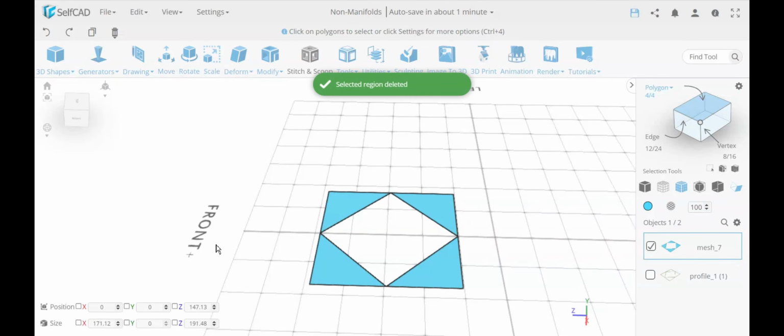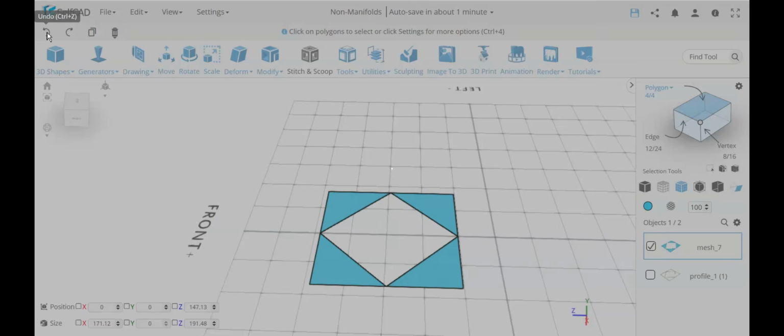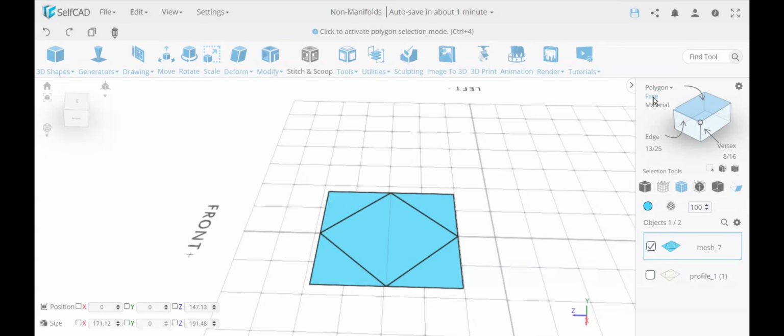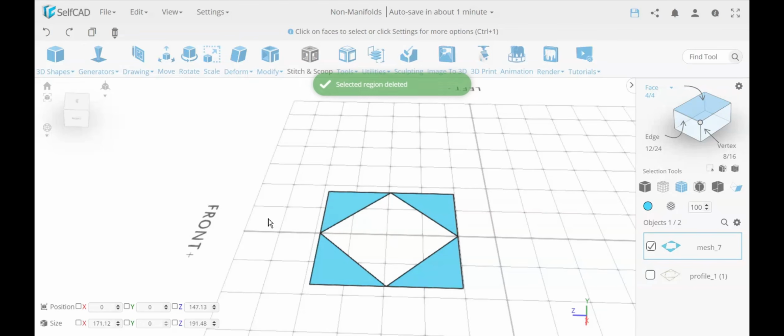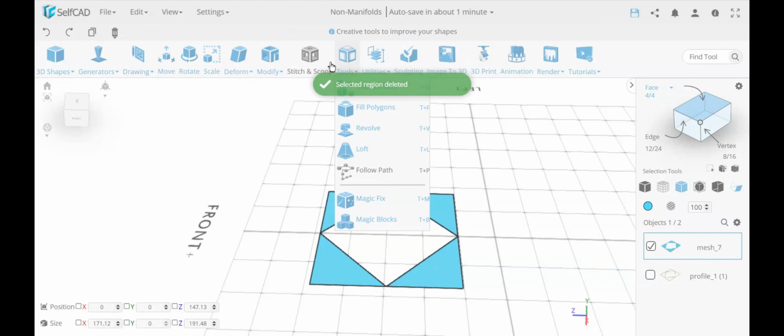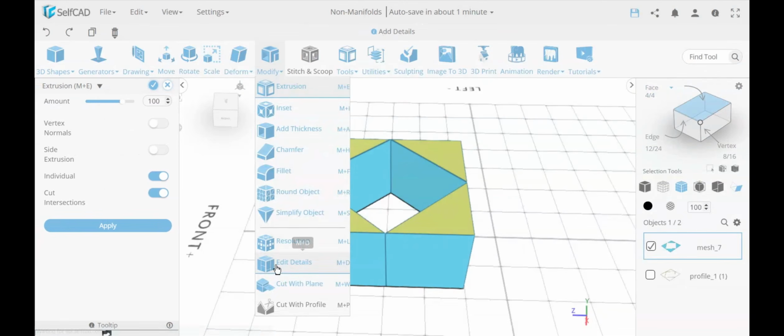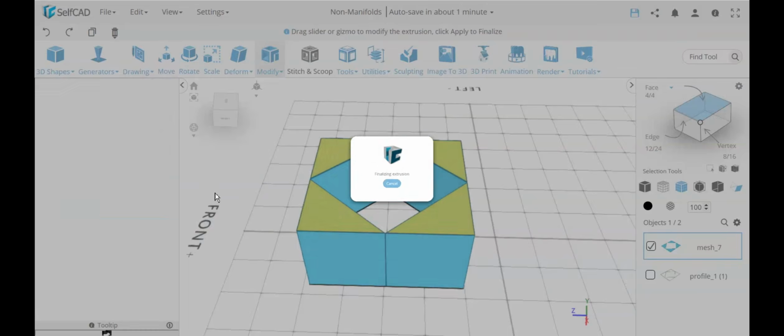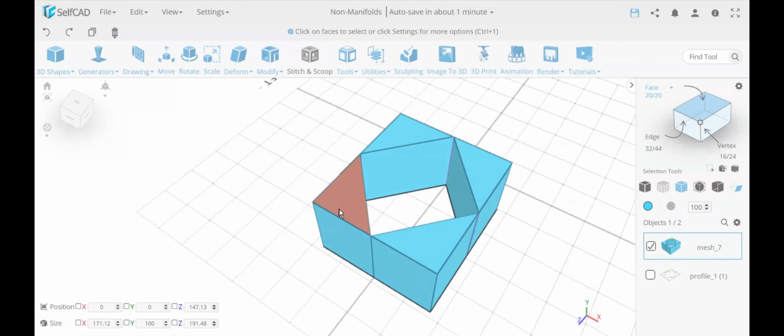Okay, so now what I'm going to do here, actually I didn't need part, it's a single face, I could have used simple face selection as well. So let's see, if I do something like this, I can just go to face selection and simply select, it is two faces, okay, so I wouldn't need to click twice. Nevertheless, if I now do extrusion or add thickness, doesn't matter which tool I use, I got this shape, and again, this is non-manifold, the same problem.